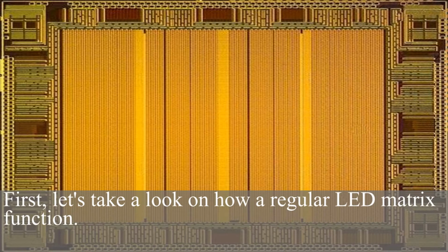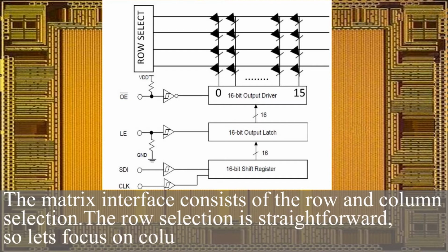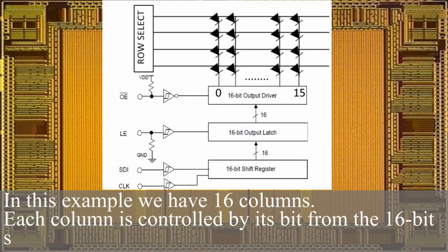First, let's take a look at how a regular LED matrix functions. The matrix interface consists of row and column selection. The row selection is straightforward, so let's focus on the column part first. In this example we have 16 columns. Each column is controlled by its bit from a 16-bit shift register.